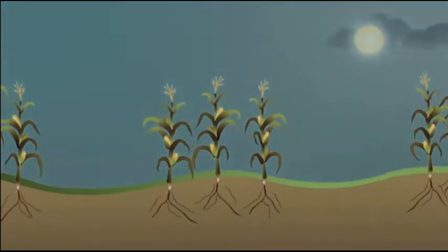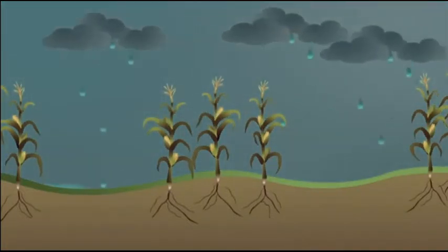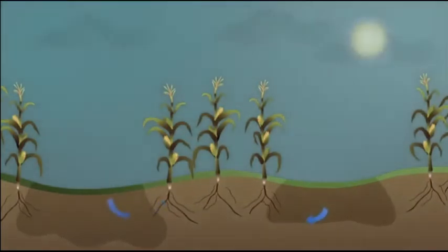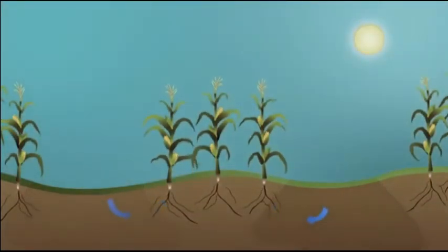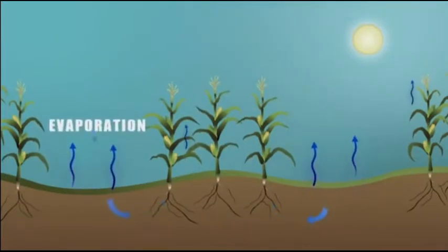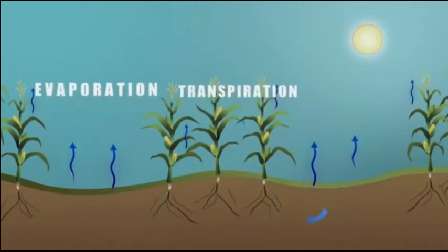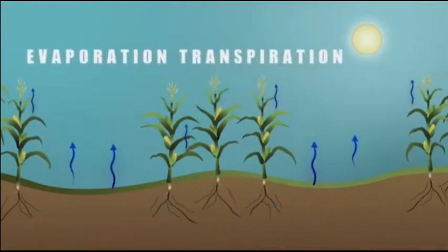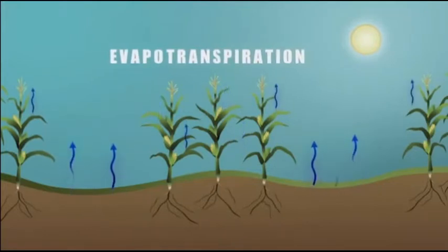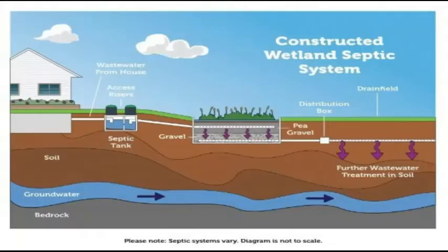The septic tank system usually consists of septic tanks, which have a baffle that divides the tank. The settling process takes about 24 hours. Only the primary treated liquid or effluent found in the central level of the tank flows out of the septic tank into an absorption field. The sludge and scum remain in the septic tank and must be periodically removed to ensure the system operates properly.